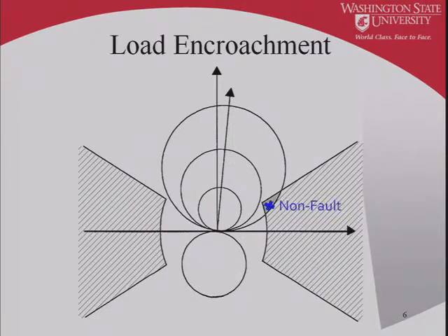So when you get a point in this graph coming from the relay registers its value, it will drift over time. When it gets out of that intersecting area, into the circles, it becomes a fault. And setting up these settings is the challenge of load encroachment.